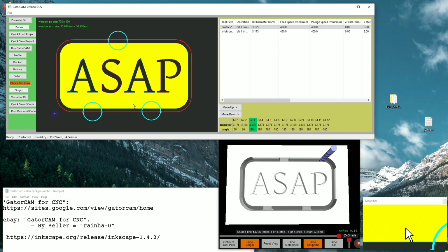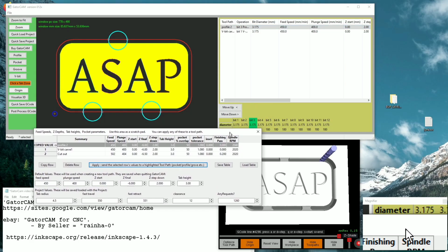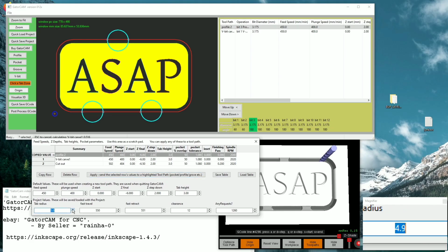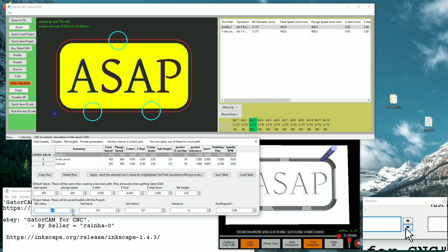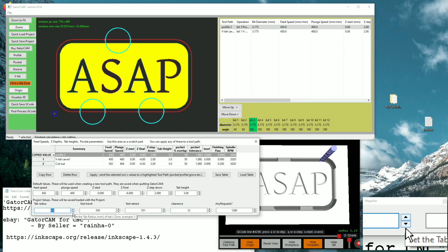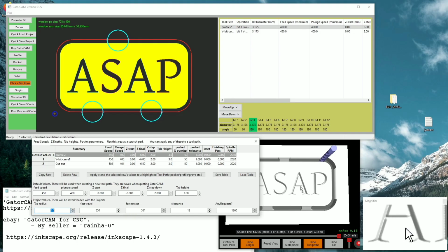So also the tab radius, if you want to change the tab radius, right click on a profile or any toolpath, and down here there's a little tab radius box, and you can increase it and it instantly gets updated here and here. Let's watch that again. So if you go too small, your tabs aren't going to show up. So I usually leave them about 5 millimeters. You don't want too much to sand off. And that's usually good. That holds them in there.